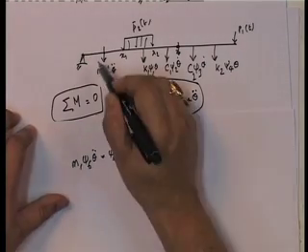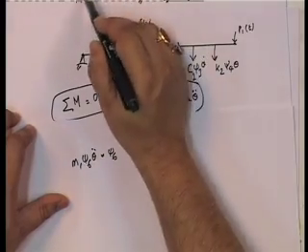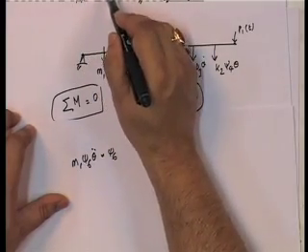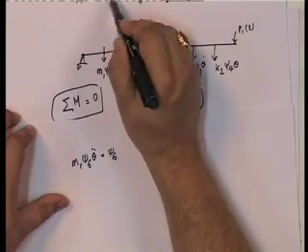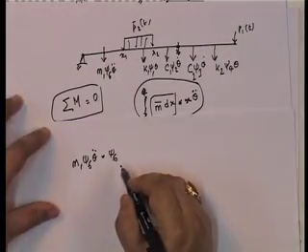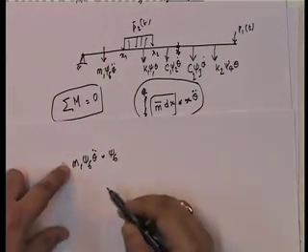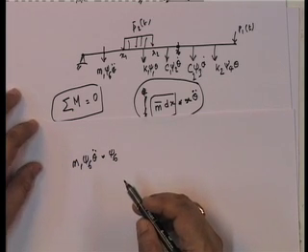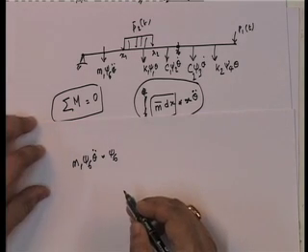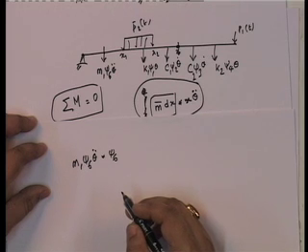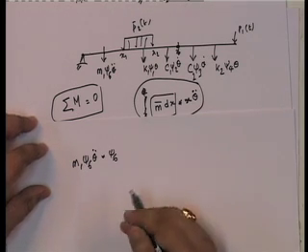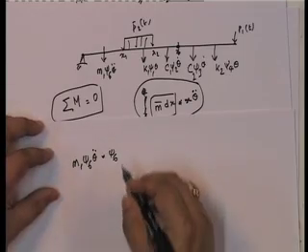That is the only reason why this is xi 6 theta, because theta is this one. All of them are L theta. So, this one is going to be xi 6. Since all of them are clockwise moments, I am going to take clockwise as positive in this particular case. If you take anti-clockwise as negative, all that will happen is that you will get them all as negative. That is all, it does not matter.